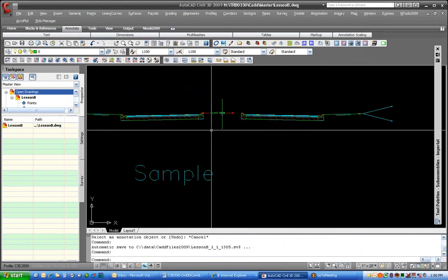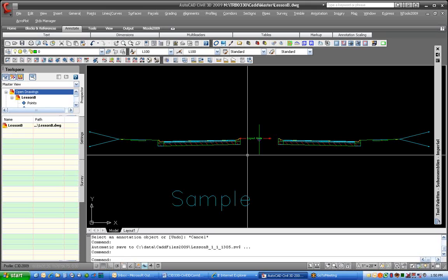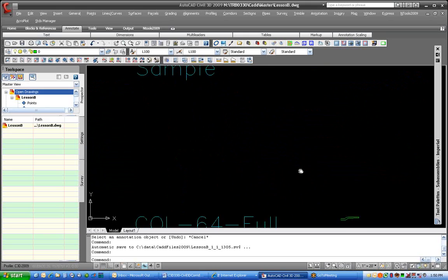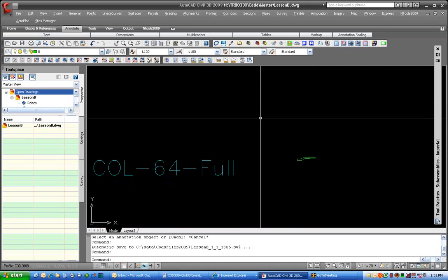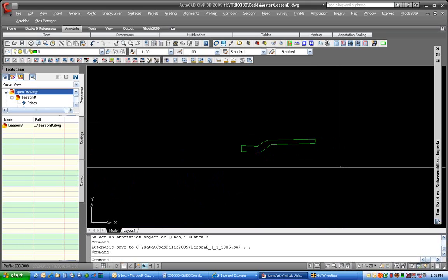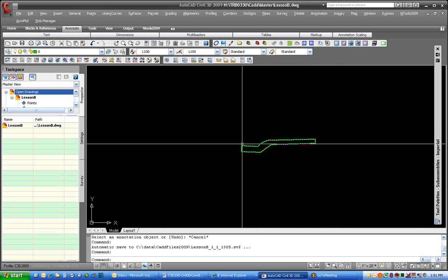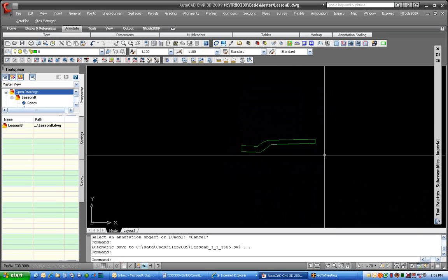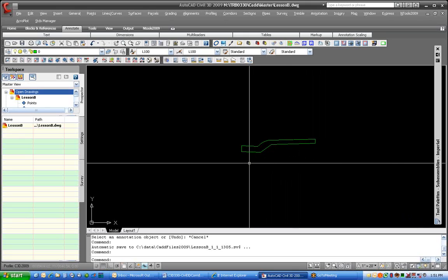I've got one assembly already done. This is what I want to end up with, basically an assembly that looks like this with our components hanging off of our assembly marker here. I'm going to modify it just a little bit. Instead of using the stock urban curb and sidewalk, I've got a custom sidewalk that I've drawn as a 2D polyline, and it has a gutter pan, then an arced rolled curb shape, and then a built-in sidewalk, all as a single piece. I'll convert that to a sub-assembly, and then we'll attach that on the back of curb to finish it off.